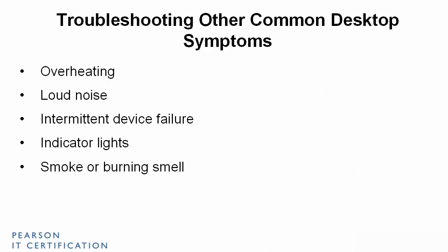Usually smoke or a burning smell is going to be coming from the power supply, and that means it's about to fail. You're not going to have much time with this, so you've got to act quickly and get rid of that power supply. Just recycle it. You're not going to want to do anything with that power supply again. Swap it out with something good.